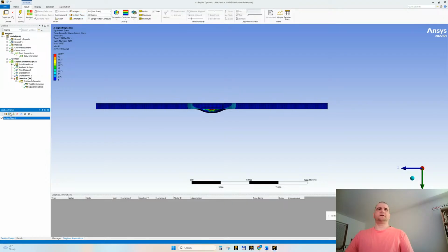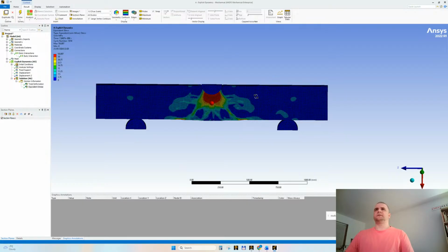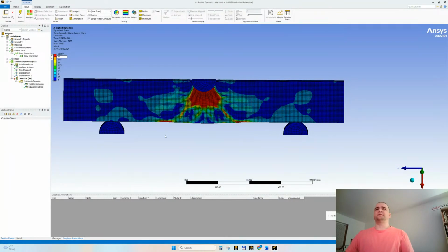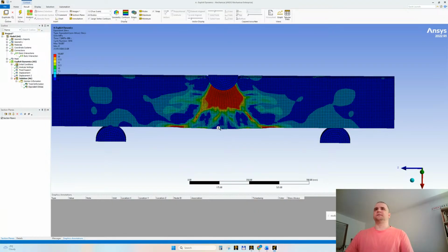Something like this. Click Edit Section Plane. We're clicking on the hidden line, and this is how it looks. Let's make it 20 in order to better see the ramifications, okay? There is a tendency, we can see that it's kind of concrete, but something is missing, yes? It's missing a stiffness, let's say this vertical stiffness.